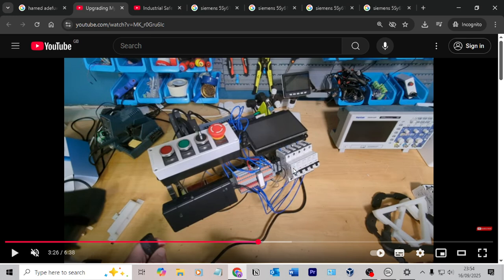What's interesting here, and the wiring here is so bad looking at it, now that I'll have drawing, I'm going to redo this wiring properly. I've got the wires coming out the bottom of these X0 terminals, going into the bottom of the MCBs, which to me, you always go in feeds in the top, out the bottom. Quite a simple circuit really. Do I have 5 MCBs there? I don't have 5 MCBs in real life.